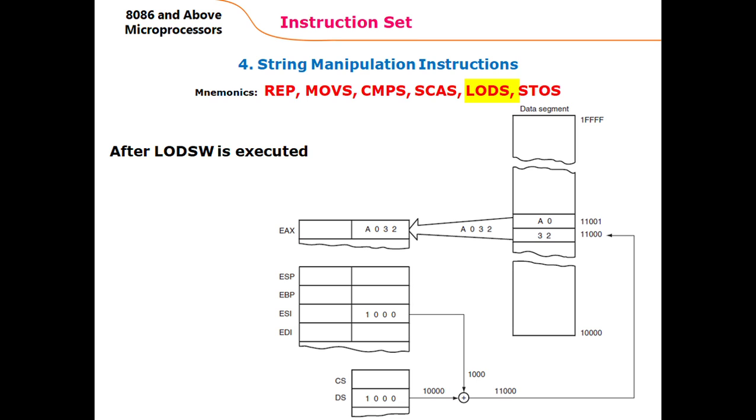And this calculation, or these operations, happen in this order. First, the 16-bit value from the data segment register is taken. It is left shifted by 4, so a 0 is introduced here, and that is also equivalent to multiplying it with 16 in decimal. And then the offset address from SI is added. So a physical address or memory address is calculated.